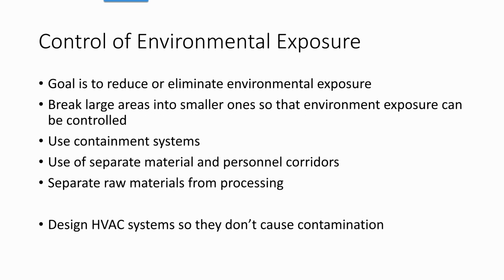So, the other real general principle of controlling environmental exposure is obviously the use of containment systems. If you can eliminate the risk of exposure of the product to the environment itself, you should do that as much as possible. So, usually the levels of protection are predicated on what the exposure risk is. Is it where you only risk exposure for a small amount of time, or do you have no exposure risk, or is there open use? So, if you can, you should use containment systems.